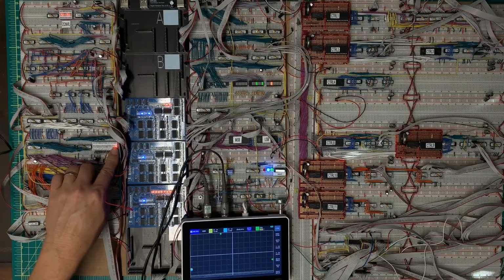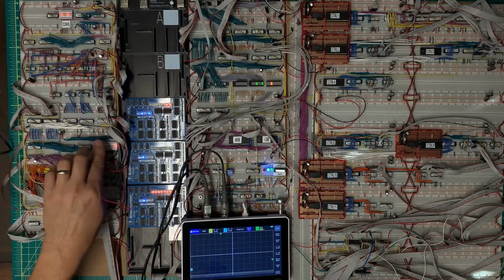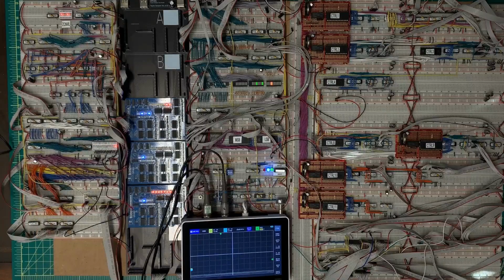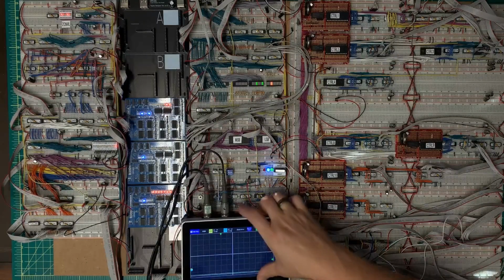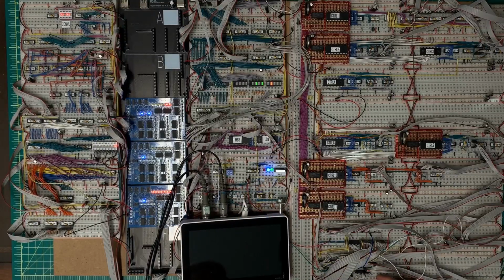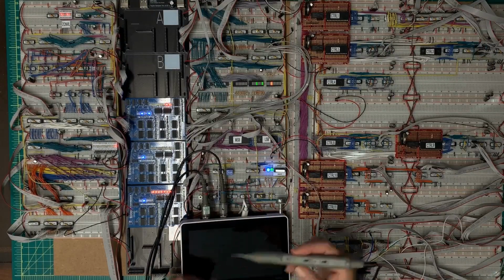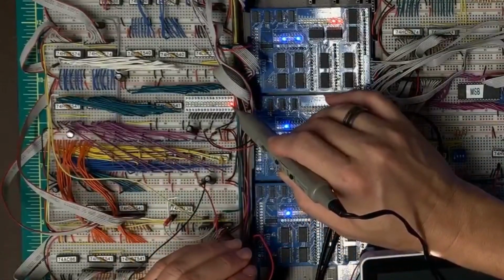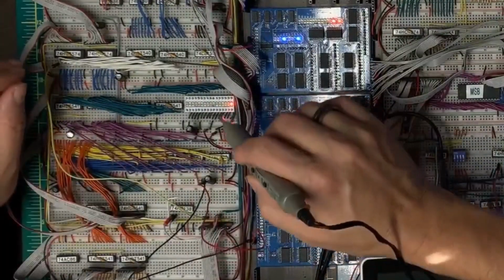That also changed the inputs here, which should be completely disabled. So something is still being asserted out onto ALU A or ALU B. I'm not exactly sure where that is. Let's start with that because that is a concrete problem at the moment. So I will power this off and disconnect power on it because that's part of the problem I have with that. And let's figure out exactly what is driving that LED high.